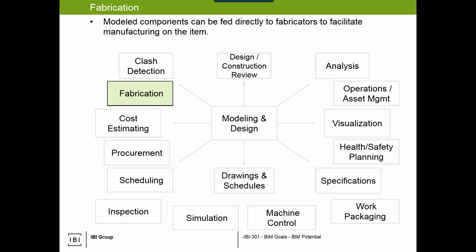Fabrication. So these are now the custom or other uses that you can hear of and think, how could that work? So this example, if I have a steel model, I can feed it to a tool like Tekla. It can build some connection details and analyze the content from the model, verified by an analytical tool, and then fed directly to a steel fabricator, and then component delivered to site. Skip the drawings, skip the shop drawings, skip the detail drawings. Sounds great, but think of the risk, especially if something's wrong.